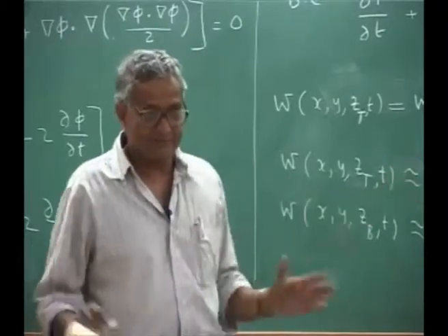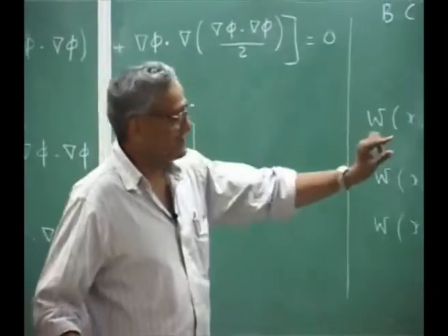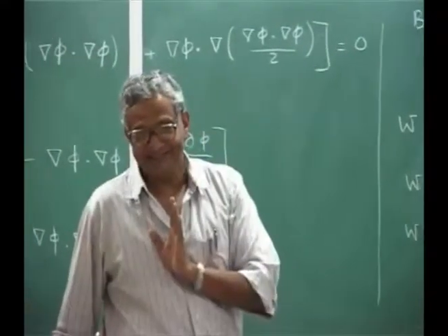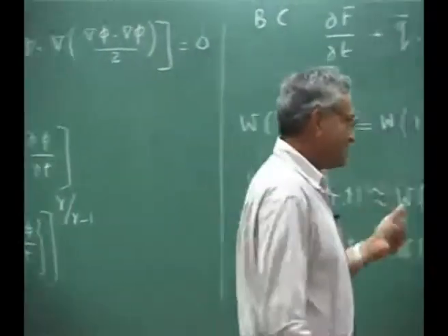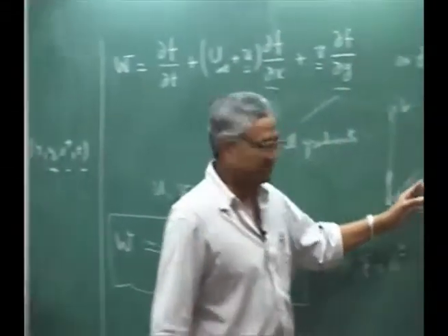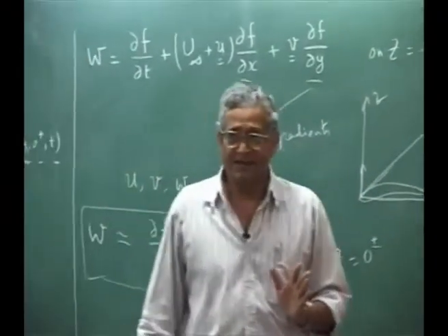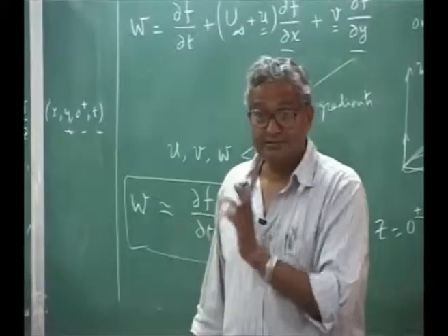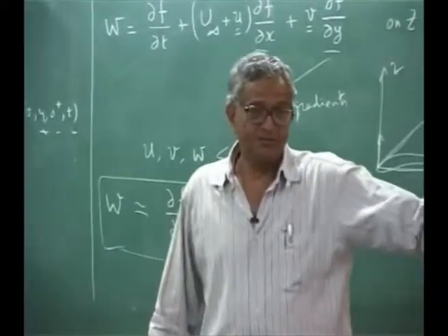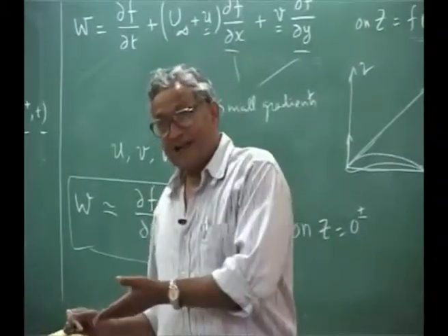In the sense, you have so much of disturbance. We are saying our surfaces are thin surfaces, lifting, because that is where aeroelastic problems are important. That's why this assumption is made. Thin aerofoils, that's good enough. And finally, the proof is, if you can get a solution which matches with an experiment, that is where the theory gets validated.